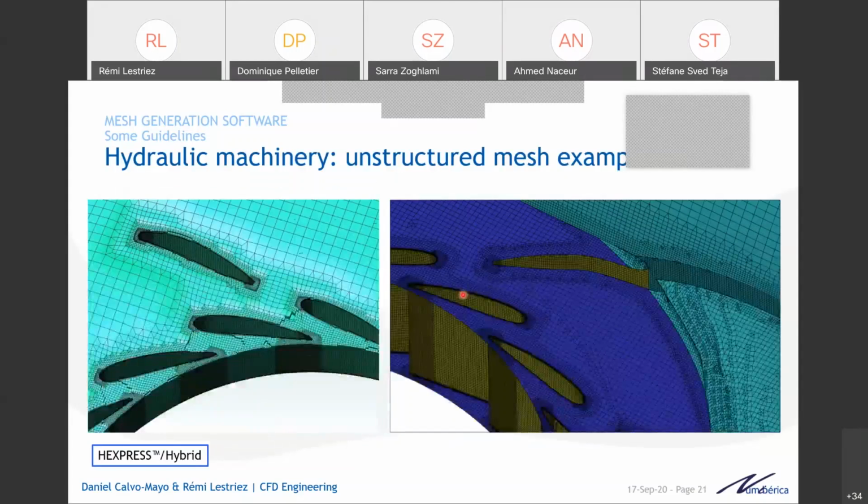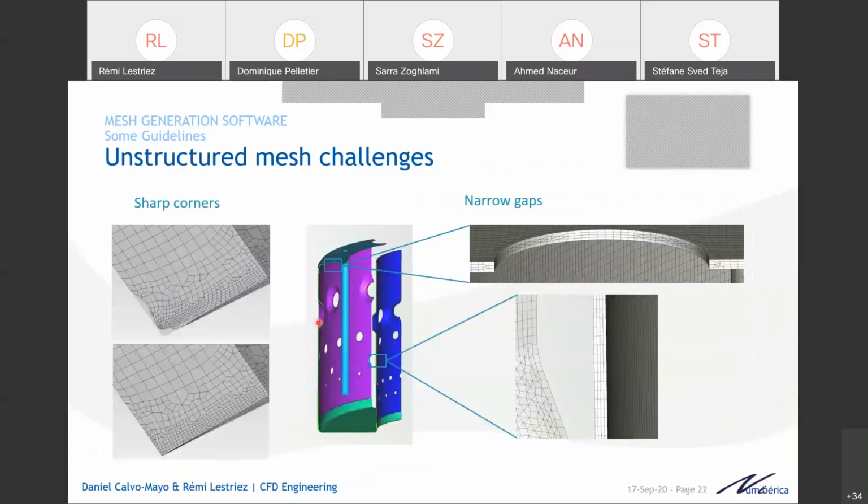This is another example of a mesh. In this case, we also have the guide vane. You can see that this would be terrible to try to mesh with a block structure. It's a very sharp angle. It's a spiral casing, so if you want to mesh it, you have a structure that is going at itself. It's the snake that is hitting its tail. So this is very, very difficult, and typically we use this unstructured mesh for this configuration.